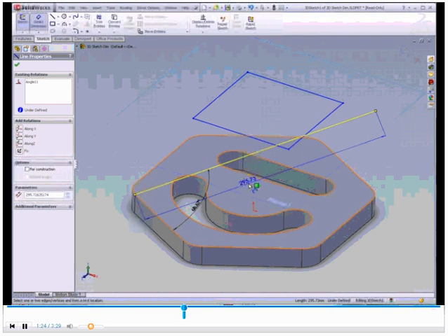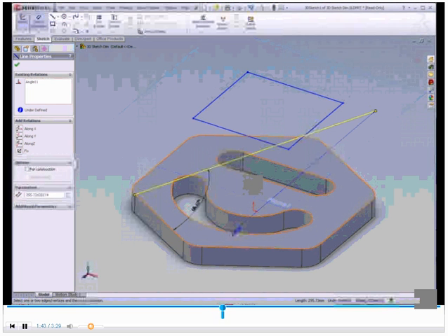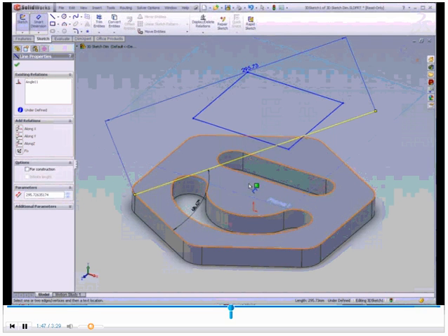The other thing, as I said, is for linear dimensions along the object. So you see currently I've added a dimension which is along the line. I can cycle through the different possible tabs. So I'm creating the dimension along the x-axis, hit the tab key again, and now I'm creating the dimension along the y-axis, and this one's along the z-axis, and then back to the straightforward linear dimension.